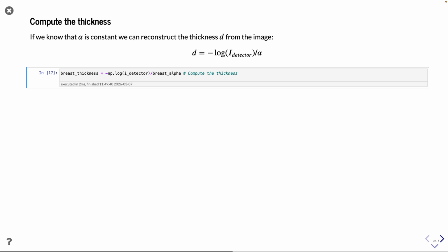That can be a science of its own to get the right attenuation coefficient. For constant materials, it's easy. Then you can just make a couple of thickness measurements, see what the transmission is, and then you get this coefficient. If you have natural materials, the variations are much more, and then you should probably do a computed tomography to get it.